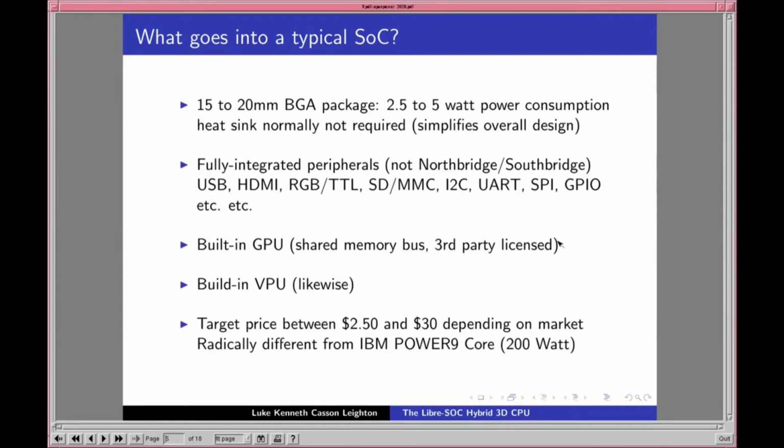you end up with proprietary software for the video decode and proprietary software for the GPU, which impacts you: you've got these opaque blobs and you can't do software development on them. When you single step into the thing, it's been stripped of all the debug symbols. So you can't work out if there's a bug in your software or a bug in the driver, which really does happen. Samsung's had that. PowerVR has just been hugely unstable and an absolute nuisance, and so on.